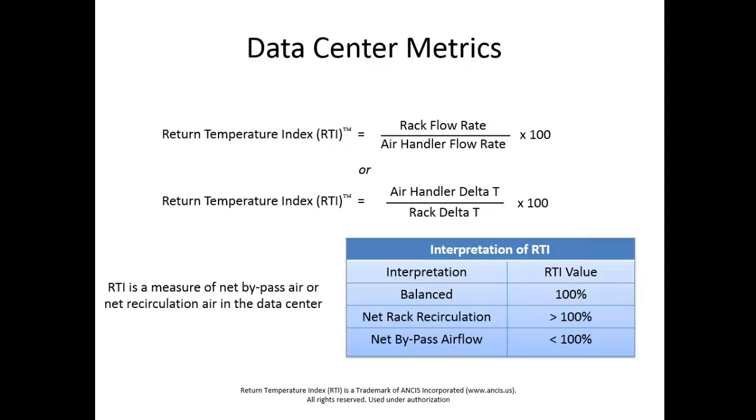Either they're going to start to stall because there's too much pressure differential across the fan, and therefore the flow rate diminishes, which causes your equipment to heat up and failure modes to occur. Or, as Magnus suggested, it's going to pull air from the backside around to the front side of that server in the rack and cause a recirculation, which would, of course, be detrimental to the life of the server.